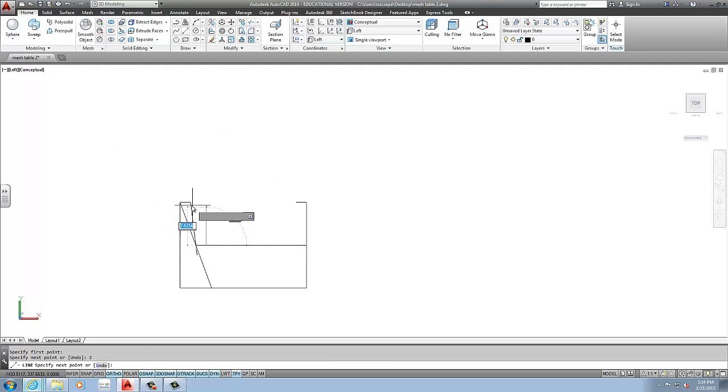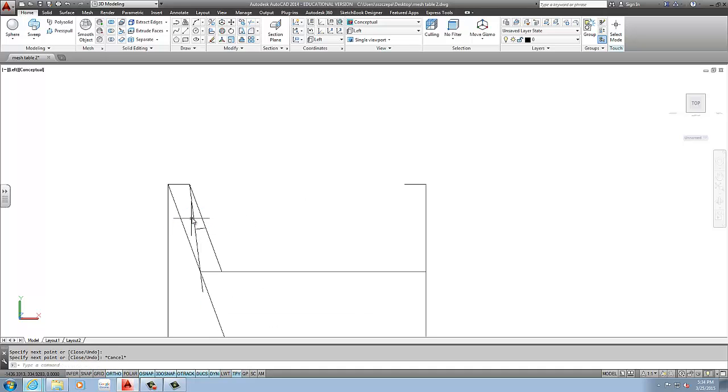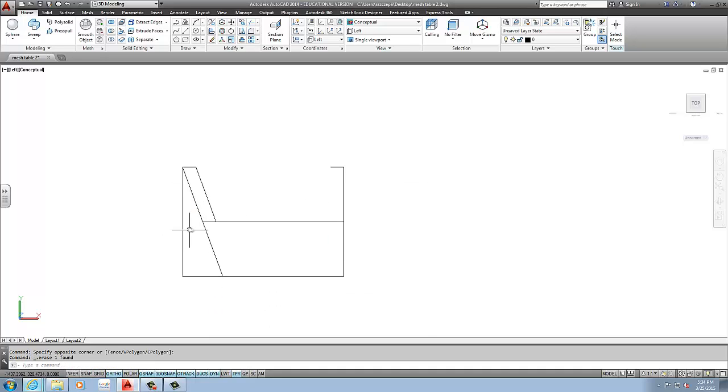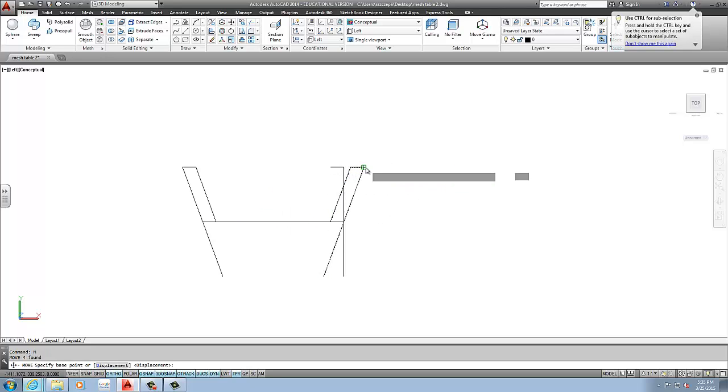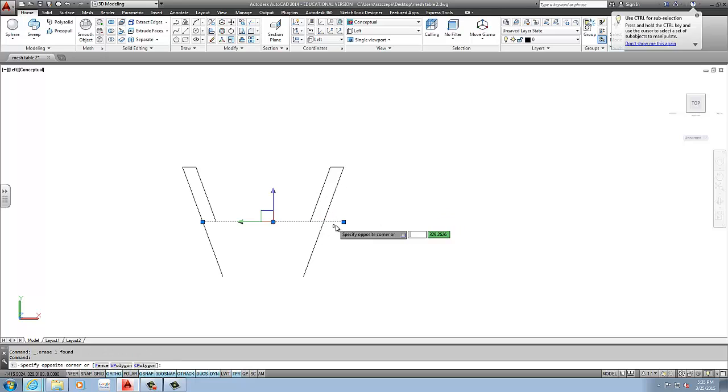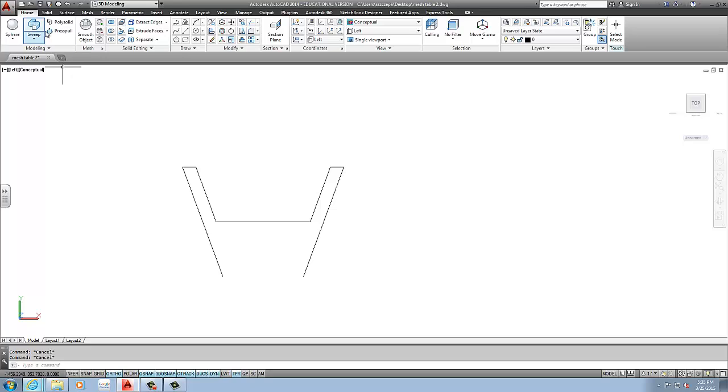I'm using lines as references to design based on the overall shape. So you can see the rest of the whole part is not moving. That's because I'm using a mirror command, so there are three lines, an exact mirror of this. Those three lines get modified when I select the corner. If I'm selecting a surface, it has these 4 lines, and only those 4 lines get moved, while everything connected to those 4 lines gets pulled away.